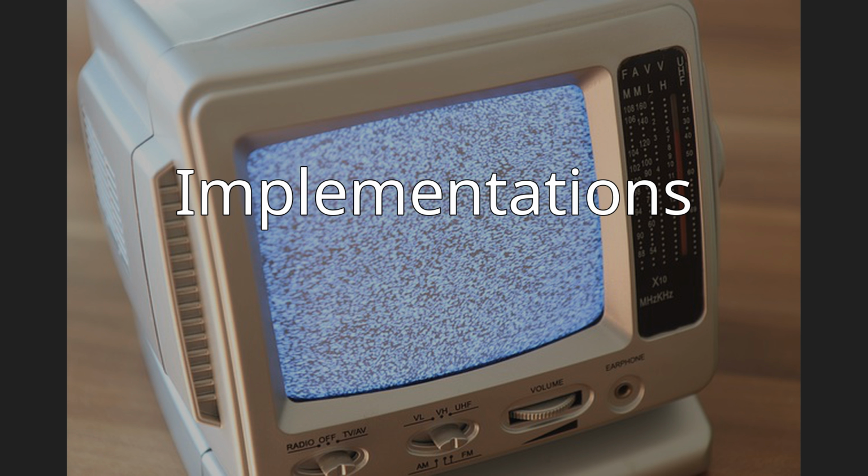Implementations. Nearly all modern DVD players and set-top boxes with Scart sockets can output RGB signal, which offers superior picture quality to composite signal. However, many devices do not have RGB output turned on by default, instead defaulting to composite video. RGB often has to be set up manually in the menu or via switches on the back of the device.